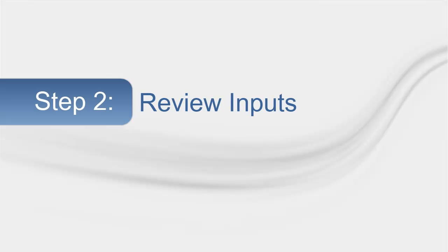Once the problem areas have been identified, a good place to start is to review the data entered. The following are suggestions that, based on support calls, are common places where errors are made. This step targets commonly overlooked assumptions in the TRACE data entry process, as well as the complex interactions that typically occur in building simulations. This is meant to only bring attention and does not necessarily require action to ensure the model is set up as intended. Each building model is unique, and the impact of each of these steps may be different.